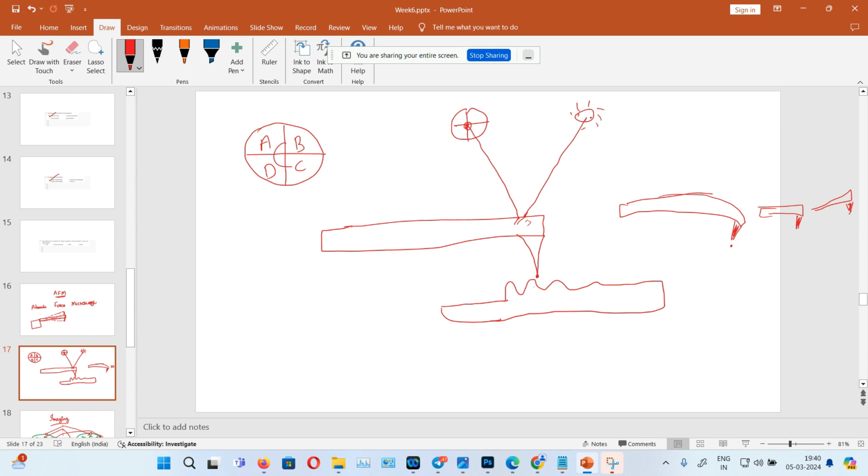If the laser beam is sitting equally on the middle portion of the photodetector, and there are configurations like (A+C) minus (B+D), then the current which comes as the output of the photodetector will be zero. So (A+C) minus (B+D) will be zero.